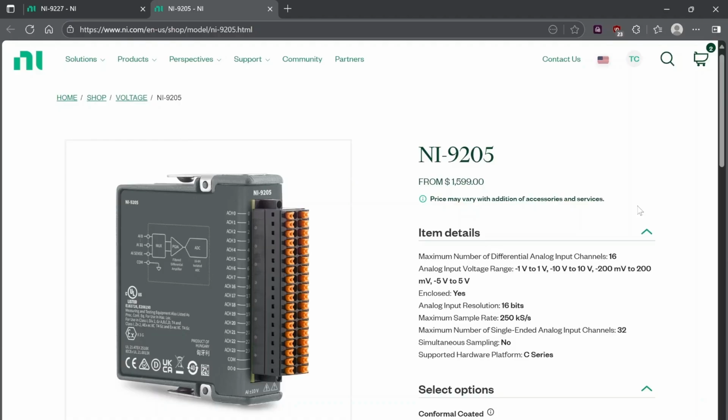But yeah, the basic idea would be I can take anything that can measure voltage and basically add a shunt somewhere outside of this, and I'm just measuring the voltage drop across that shunt resistor. And now in DAQmx, and I'll demo this in just a second, I can specify that I have an external shunt and what its value is, and then when I query DAQmx for the latest data, I'm getting the data scaled to current. So I don't need to read a voltage and then do some math using Ohm's law to convert that, although you can do that as well, right?